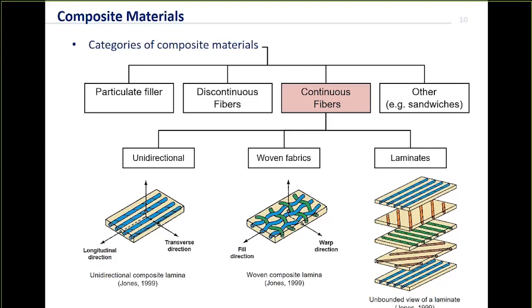It has a static strength of often around 2,000 megapascals in the fibre direction. Unfortunately, it's also fantastically weak in other directions, which means that in order to make it usable, you have some work to do, and you have to sacrifice some of that outright strength to make it more robust to loadings in different directions.